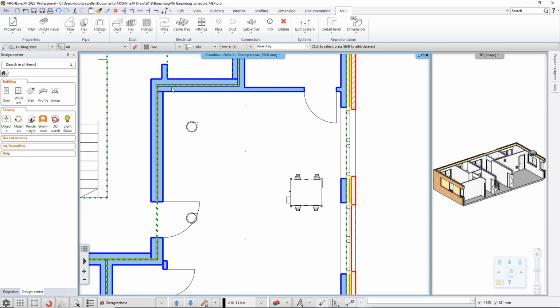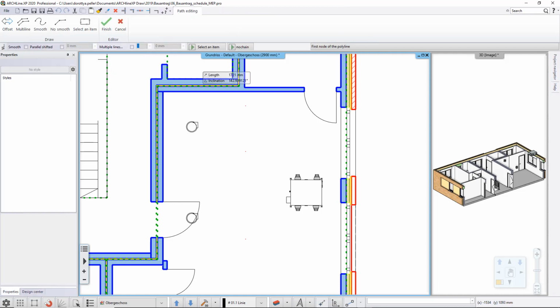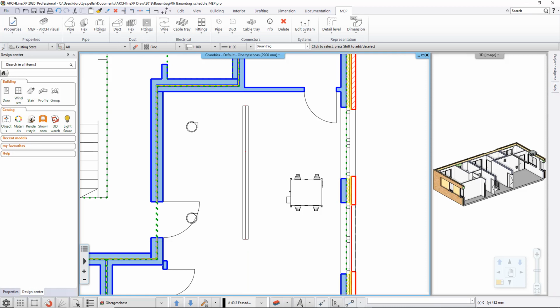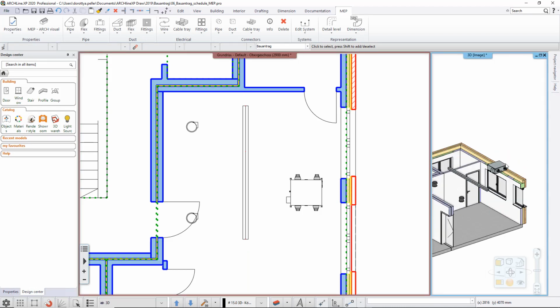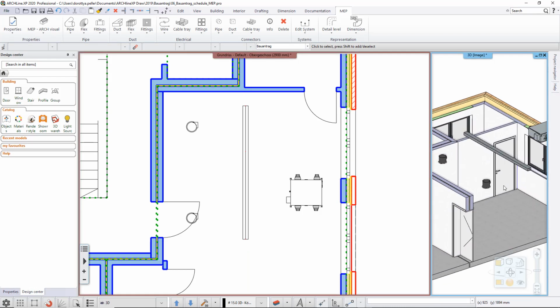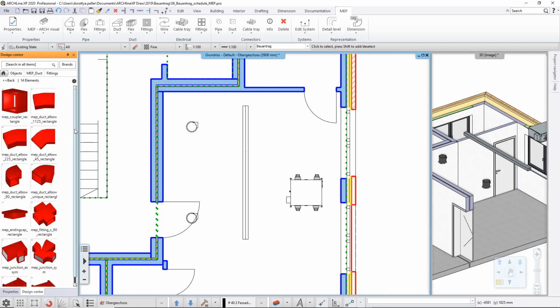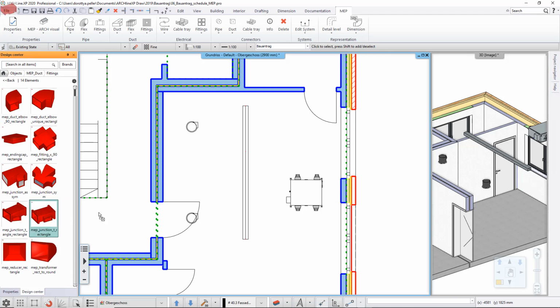I need to create a vertical duct like that. So I'm going to use the 2D editing environments to create a ductwork. When it's created, I need to check if it's actually in the right position. I can manually, horizontally move it if it's not. Now, my next task is to actually link the heater into this duct, and I do that by adding the ductwork, and I need to add the T and L connections. I'm going to add a T over there.